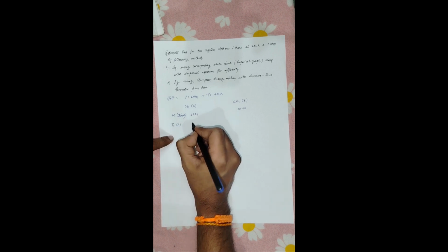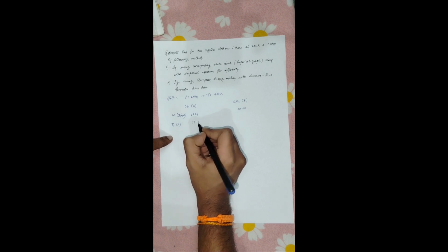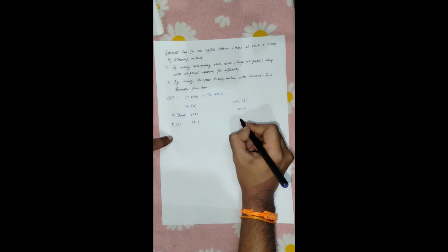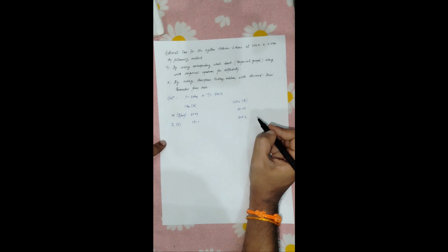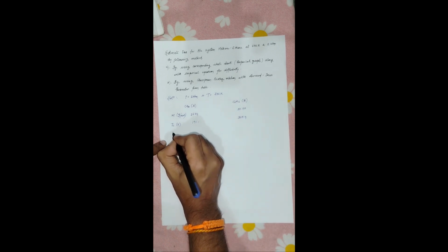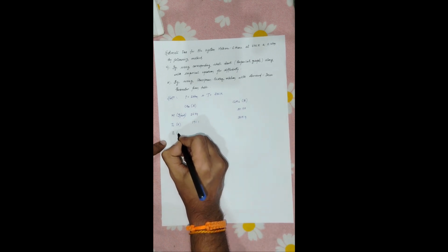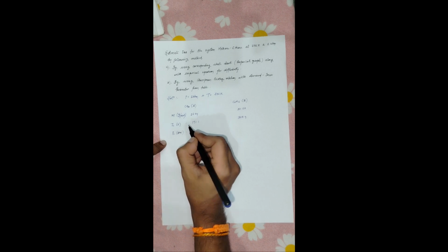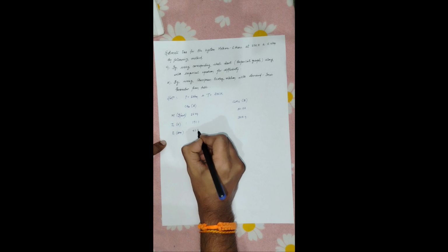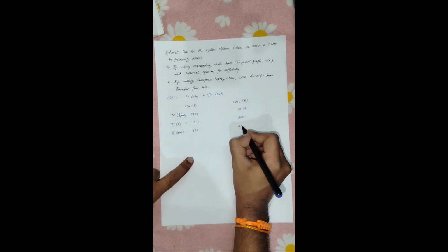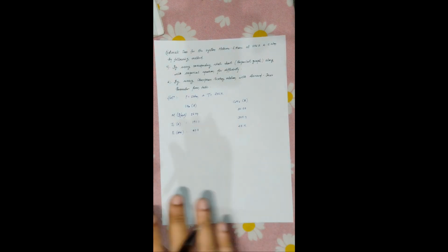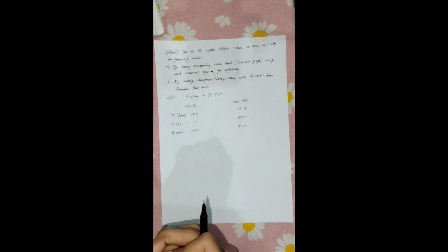So for methane, it is 191.1 Kelvin, and for ethane, it is 305.4. And critical pressure is 45.8 and 48.2 atm. So this is the required data for the estimation of diffusivity.